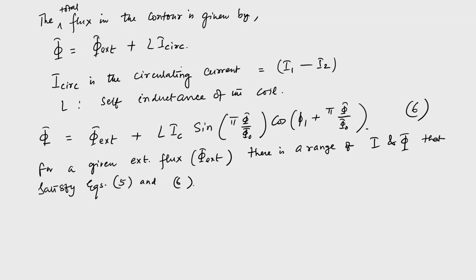And of course, one needs to know I c, which is the resistanceless current or the critical current that flows into the SQUID loop. So, let us just talk about a SQUID without self inductance. Okay.